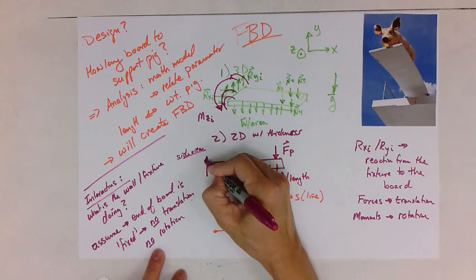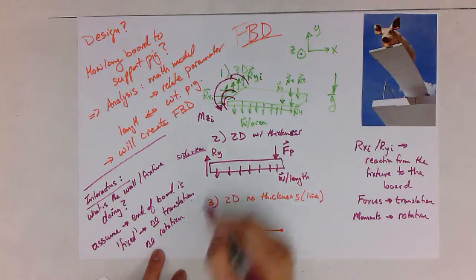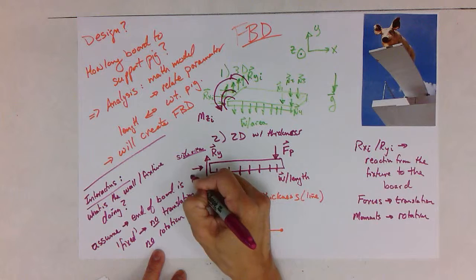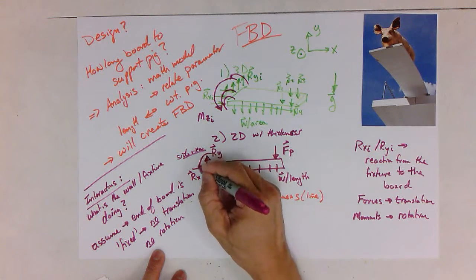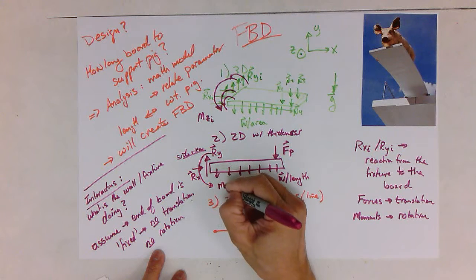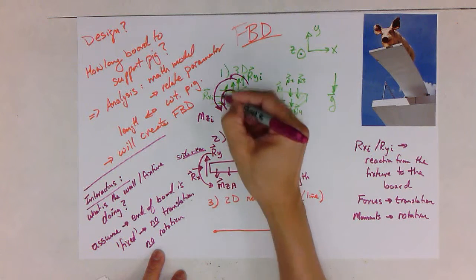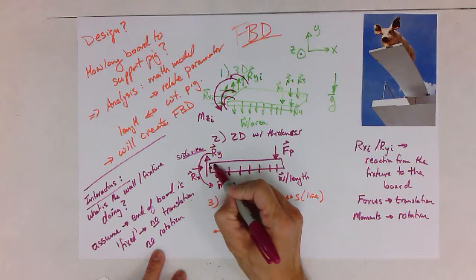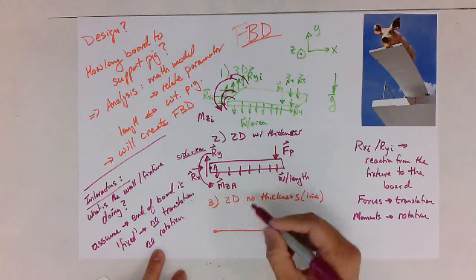And likewise here I will have a single reaction force in the y direction, in the x direction, and then a moment. And I'll call A as this end. So this end here I'll call point A, somewhere here. And so that's the moment about an axis which is passing through point A.